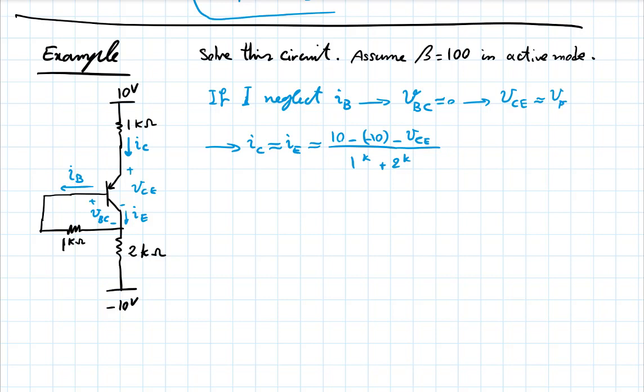Or, this is VEC, the way I've indicated it. You see, it's very easy to make mistakes when you go from one transistor to another, VEC. So VEC is approximately VEB, which is 0.7 volts. This number would be then 19.3 divided by 3, 6.4, let's say, approximately.